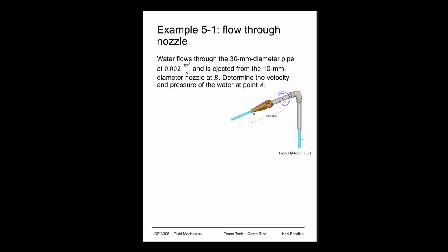So we can just say very simply, we know that total flow, that's what we're given, has to be the velocity at A times the area at A. That's just our definition of flow if we're using average velocities, which we're not given any more information, so we'll use average velocities here. So we can, of course, solve that for VA, right?